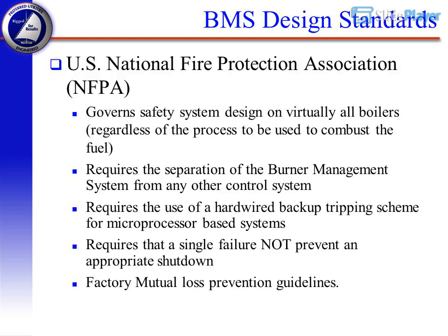Fail-safe. BMS Design Standards. U.S. National Fire Protection Association, NFPA. Governs safety system design on virtually all boilers, regardless of the process to be used to combust the fuel. Requires the separation of the burner management system from any other control system. Requires the use of a hardwired backup tripping scheme for microprocessor-based systems. Requires that a single failure not prevent an appropriate shutdown. Factory Mutual Loss Prevention Guidelines.